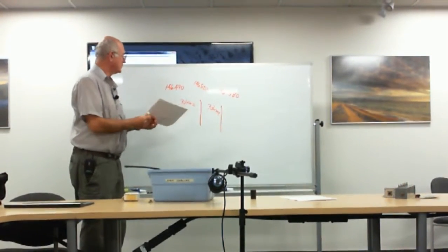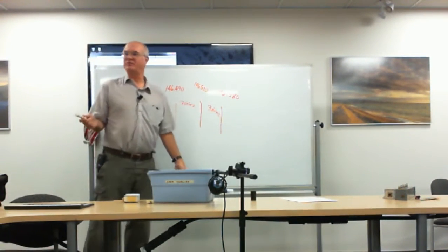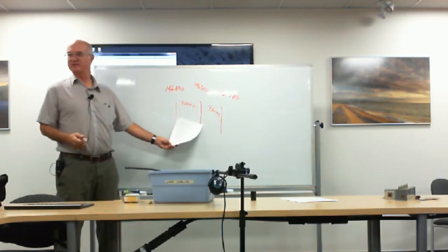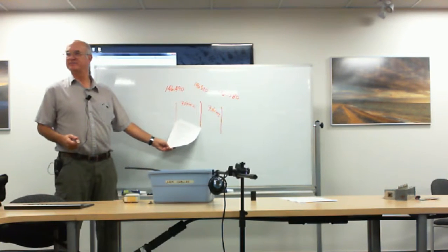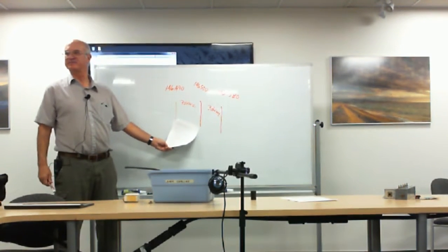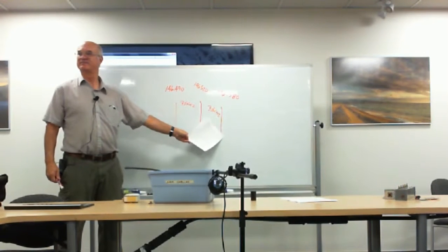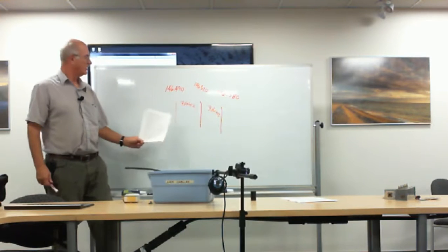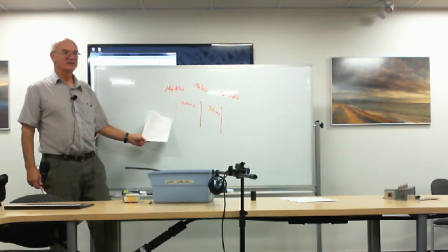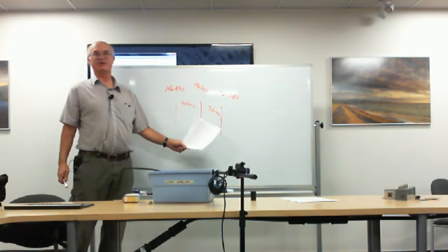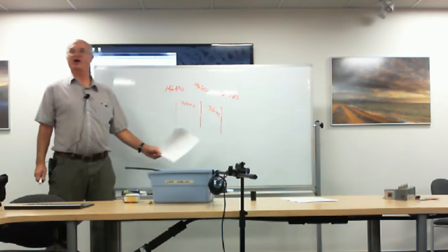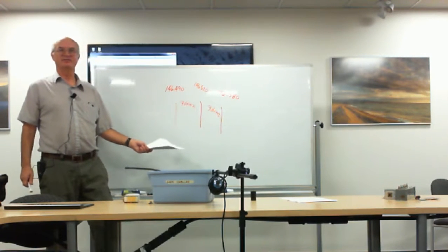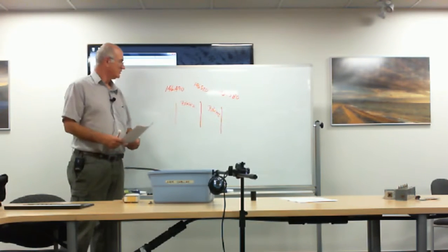Now, remember sum the difference in two originals? Guess what happens when these two are transmitting? What frequency gets generated along with others? And if these two are transmitting, guess what frequency gets generated along with others? This is a 2-frequency, third-order intermod. And this is the most common intermod, and it will be on the test, that you're going to run into. 2-frequency, third orders. What's going to happen?